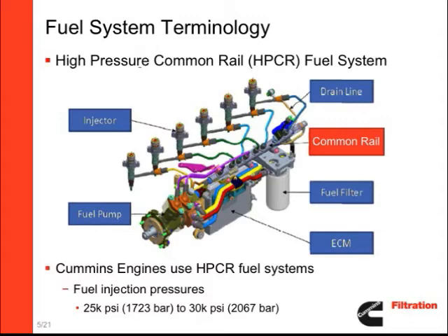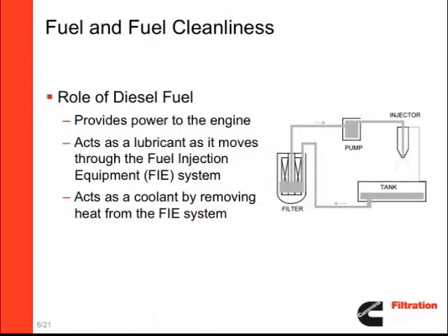These systems have fuel injection pressures ranging from 25,000 psi, 1,723 bar, to 30,000 psi, 2,067 bar. At these pressures, any particulates in the fuel are like taking a sandblaster to the internal precision parts. A basic schematic of the fuel injection equipment, FIE system, is shown here.